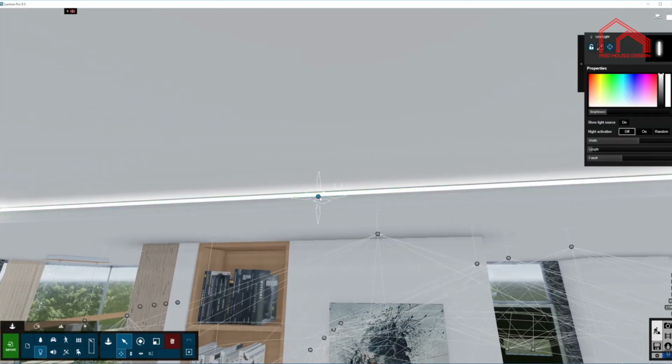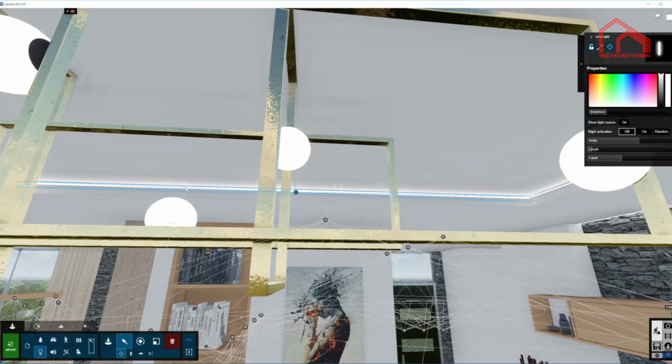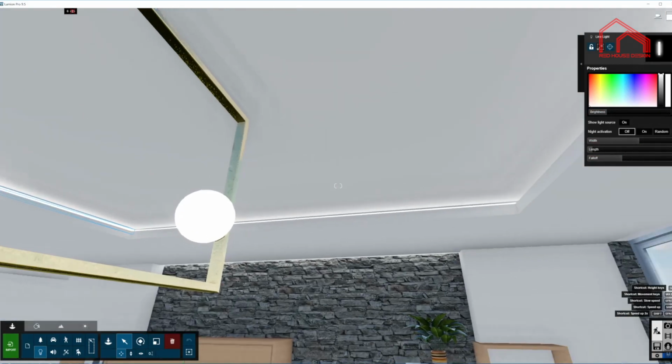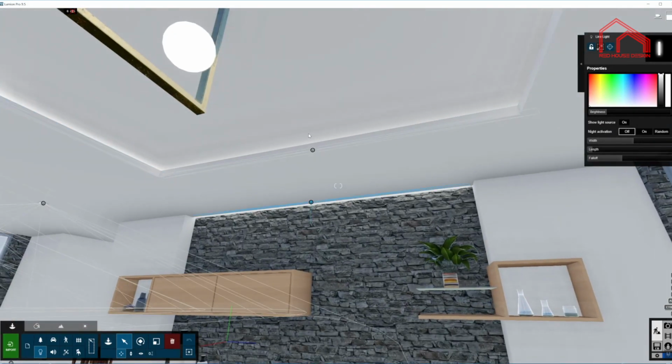As you can see, here are the line lights, here is the shape. Now this is the brightness that I'm using, and I have to obviously adjust the width and the length of the light so it does fit in the ceiling in here. And also very important, get the right balance between the brightness and the fall of the distance of the light coming from the source, because as I said before, there is another line light in here behind, basically the same value.